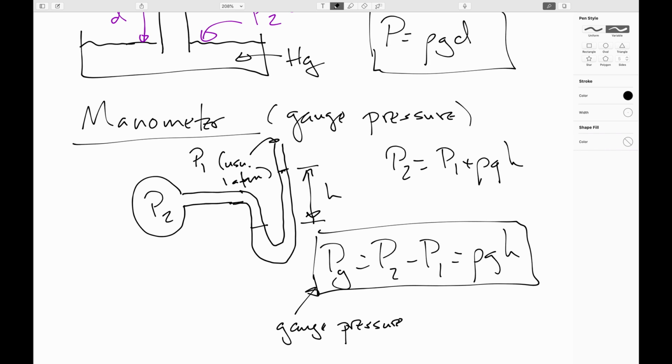It doesn't have to be much, which is why it's often measured in inches of water rather than mercury. And the whole idea is if you have a spill, you go ahead, you slam down the hood, and you get the heck out. And when you open up the lab door, air rushes into the lab, not out, hopefully keeping the chemical inside.